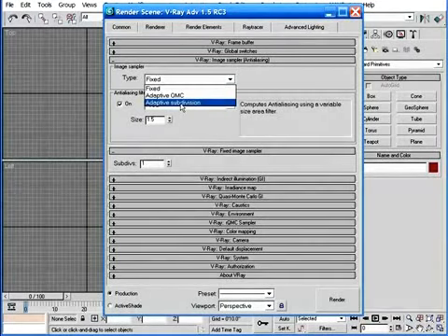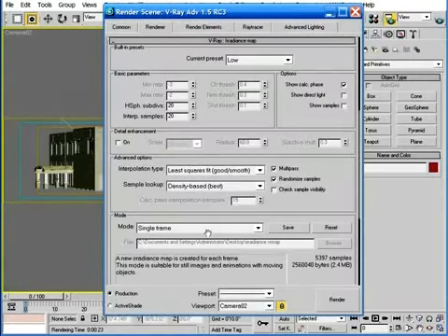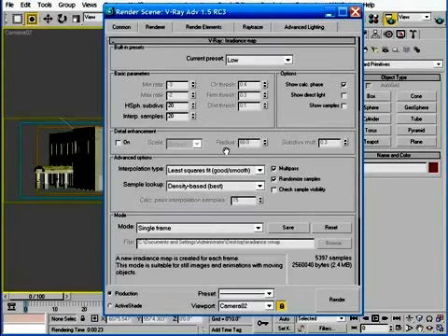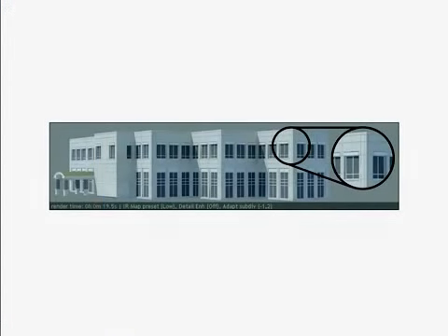So let's return to the previous exercise we were using and see how changing the image sampler can really improve the detail that is brought out in the Radiance map. If you want to follow along, you can open up the file called building02.max. And this scene by default uses the adaptive subdivision sampler. And again, it uses a low Radiance map preset with no detail enhancement. So if I render the scene, this is what the image looked like.